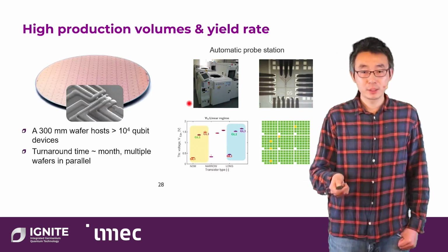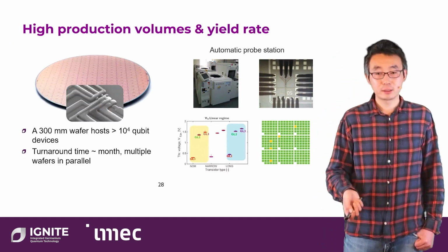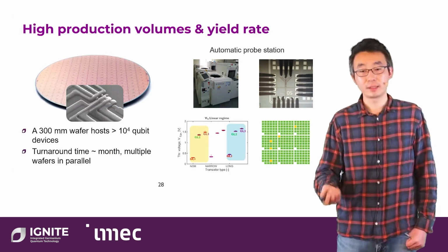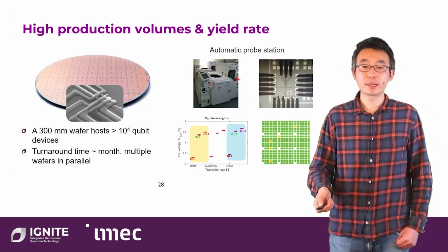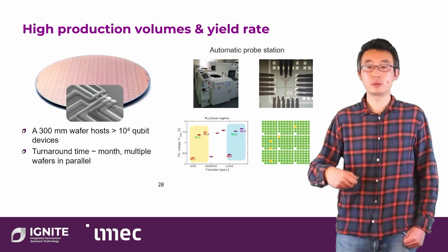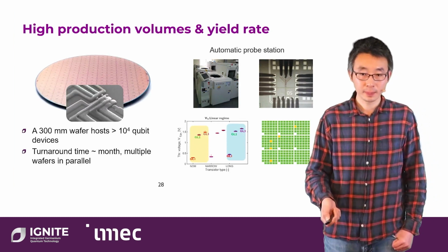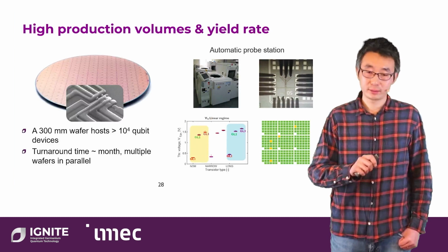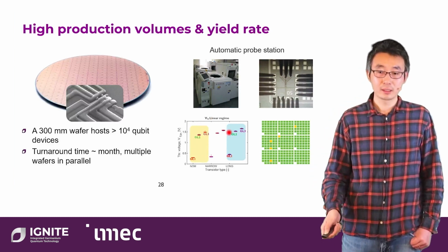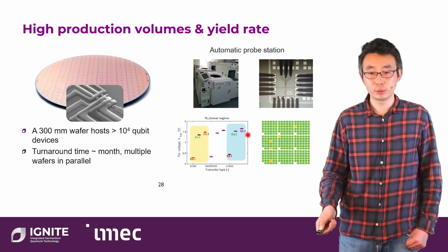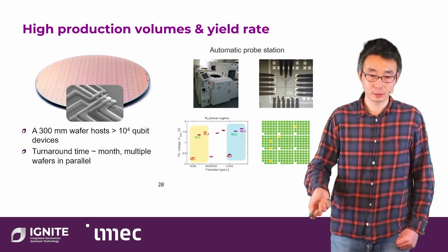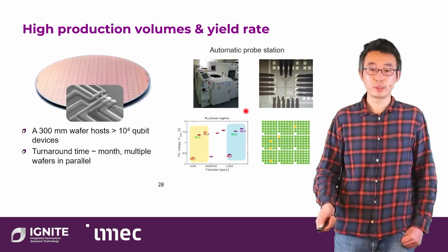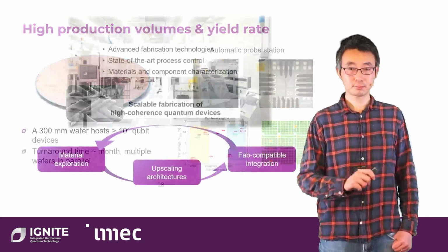If we focus on the spin qubit again, one of the limiting factors is the device yield and also the device uniformity. Here we can already get a feeling at room temperature. We can look into the effective oxide thickness across different layers, and we can see they almost sit on top of each other. And if we look into the leakage between the gates, which is also a limiting factor for the qubit yield rate, we can see the yield rate is almost 100%.